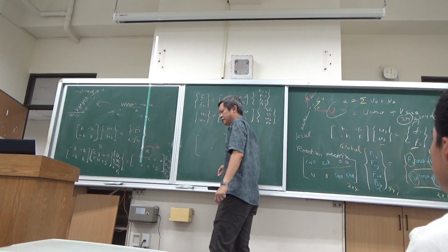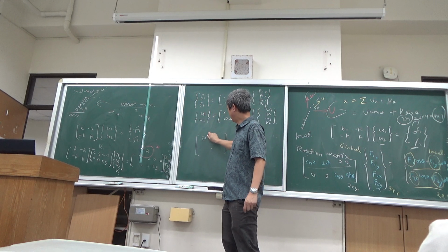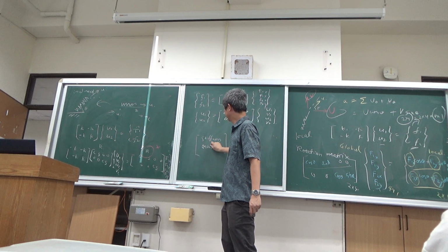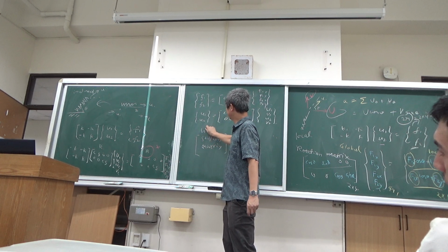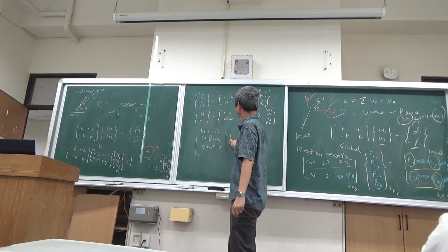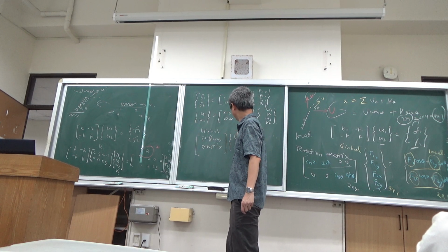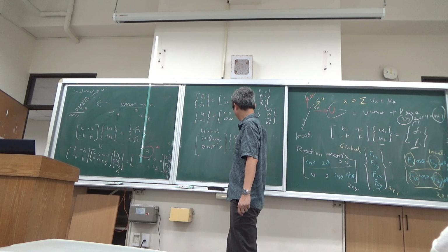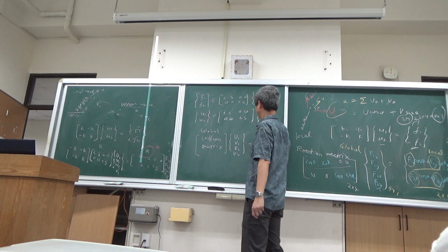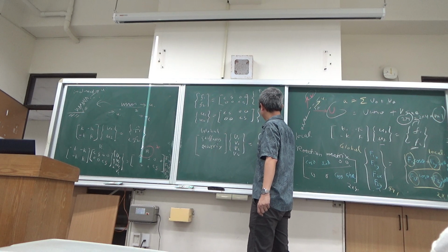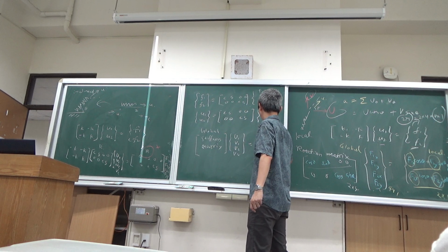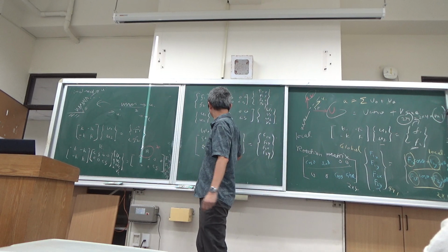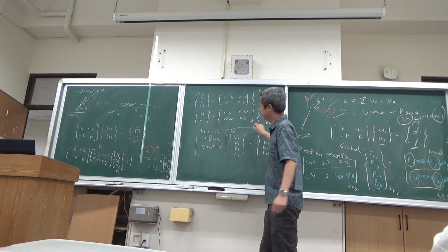What's the target? The target is I should have one stiffness matrix which is written in terms of global displacement. Big U1, big V1, big U2, big V2 is equal to F1X, F1Y, F2X, F2Y. This is all global. Okay?